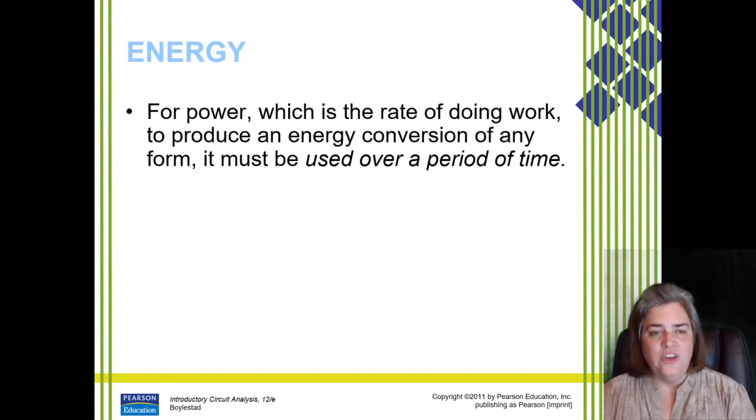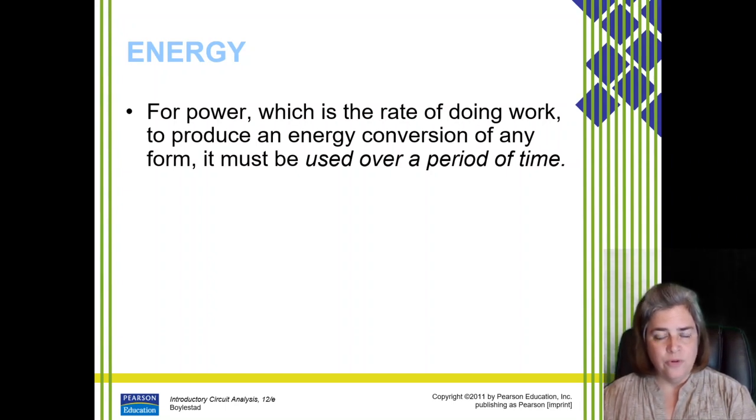Now let's talk about energy. Power is the rate of doing work. To produce energy, it must be used over a period of time. Now this is what you're billed for. A lot of people say your power bill. It's actually your energy bill, because it's your power that you're using times the amount of time you're using it.